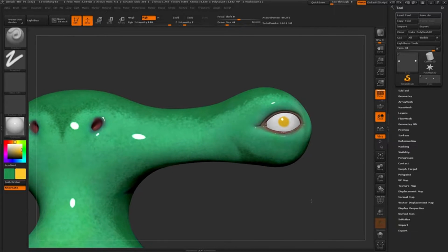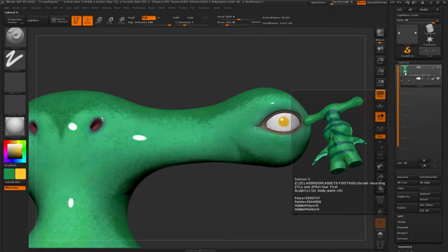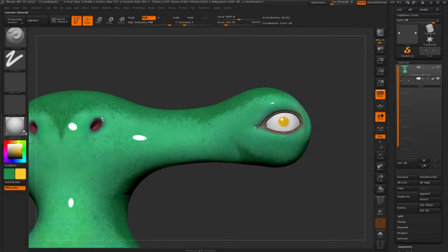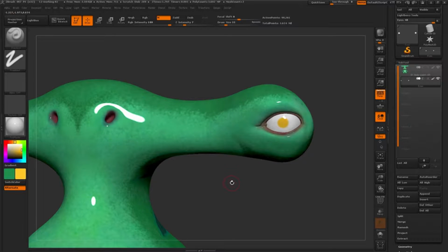on the surfaces. In order to work with separate materials on different subtools, just like the painting process, we need to fill each object with the base material of our choice. At the top we have other options next to RGB called mRGB and M. When filling objects with a base color, we've previously used the RGB option to fill with color. When M is selected, this means we'll be applying only material information to the surfaces and will not affect RGB or color information on the mesh.